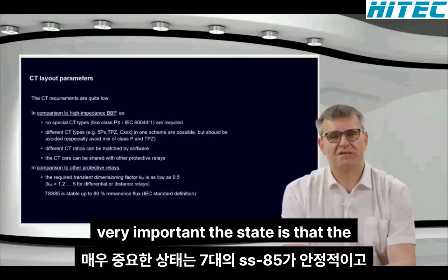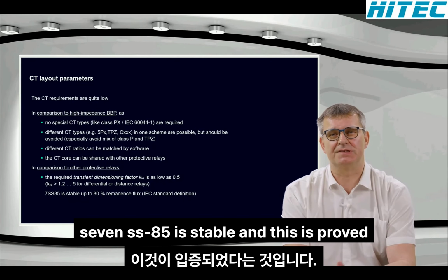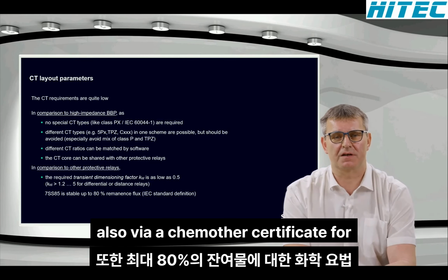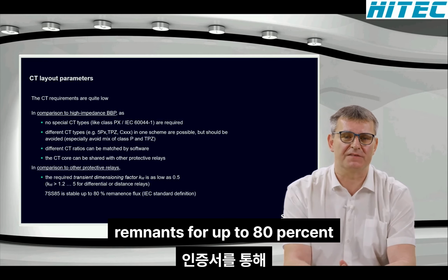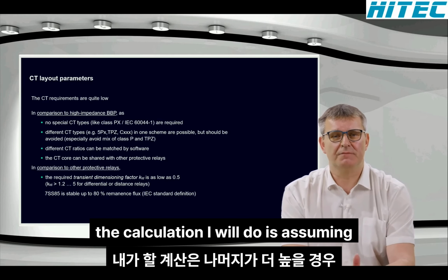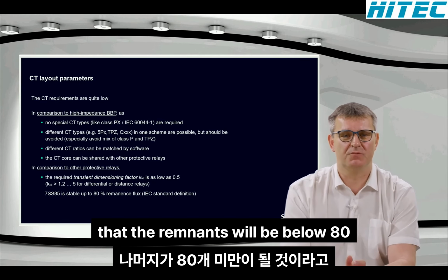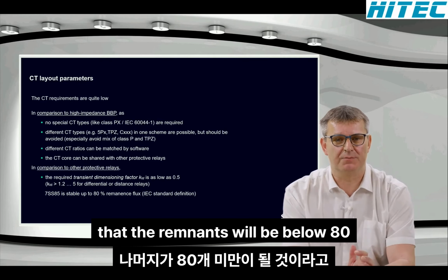Very important to state that the 7SS85 is stable, and this is also proved via a KEMA certificate for remanence of up to 80%. The calculation I will do is assuming that the remanence will be below 80%.